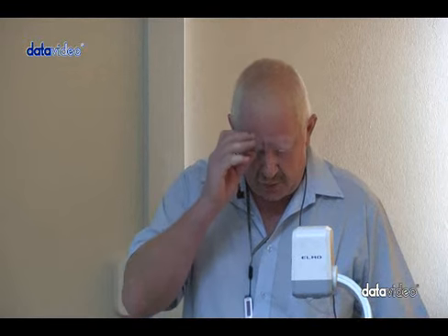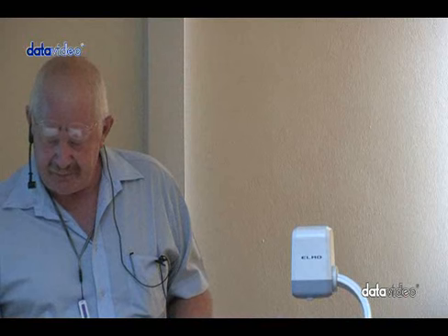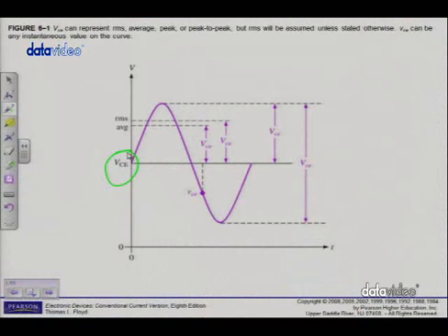Alright, but before we get there, still on page 257, just to make sure that we understand the names that are used for the quantities in this book. AC quantities; you are familiar with the DC quantities. If you can recall from previous chapters, DC quantities like VCE, we can see that the subscripts are capital letters. That of course refers to a DC quantity. If we look at these AC quantities like Vce peak to peak, for instance, I can see that the subscripts are lowercase to indicate that these are AC voltages.